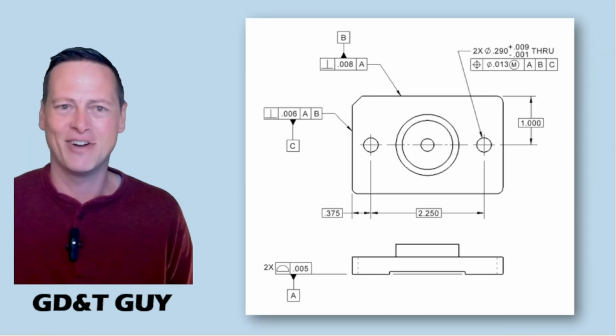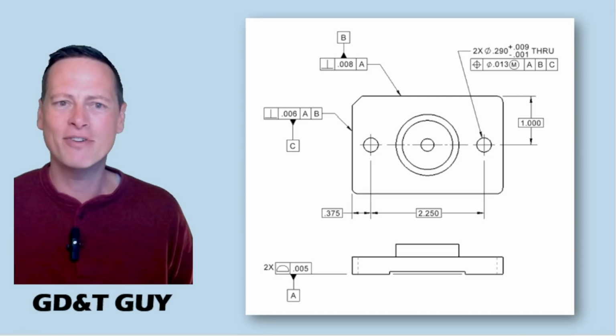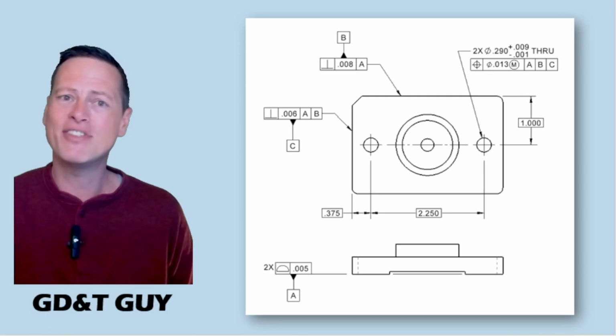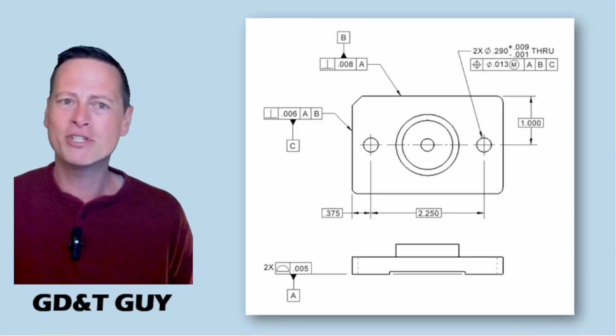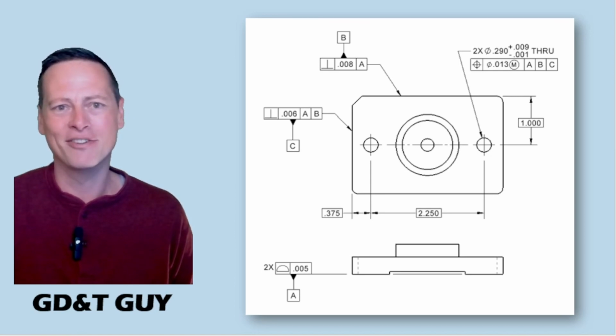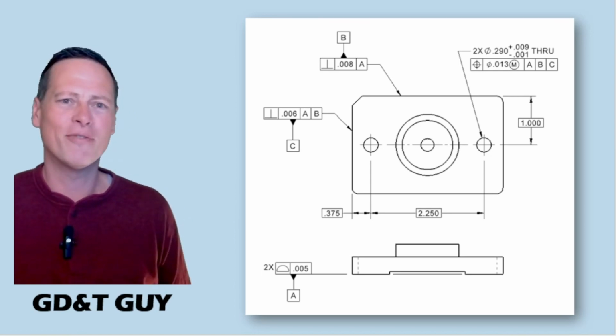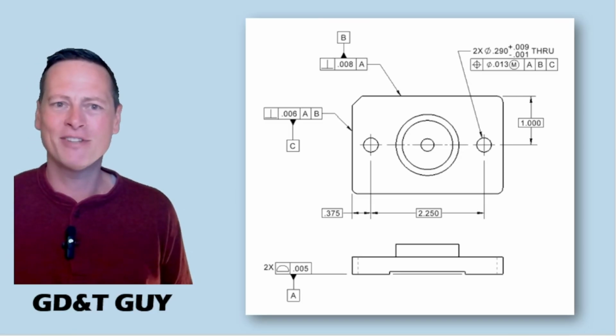Well, they're not functional datum features. Using them would impose some inaccurate requirements onto this part that we don't really need. And I'll tell you, there has been an illustration like this in every GD&T guide and course materials I've ever seen. But I would say in the engineering world, the interface that this implies, where a part like this is pushed into a corner and bolted down, it's not very common, not a very favored way to locate parts to each other. What they call the functional assembly that's illustrated in figure 4-2 for the part with datum references a lot like this, I just don't see parts that locate this way.